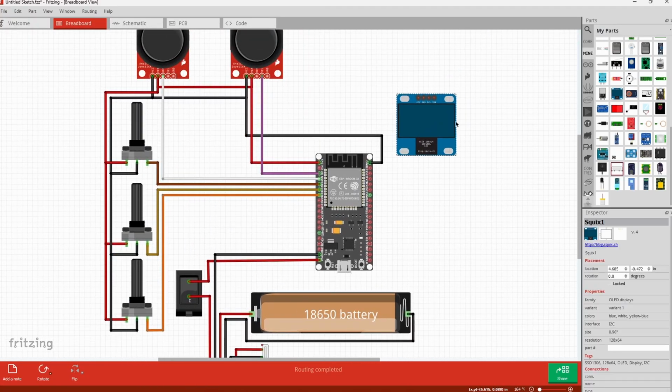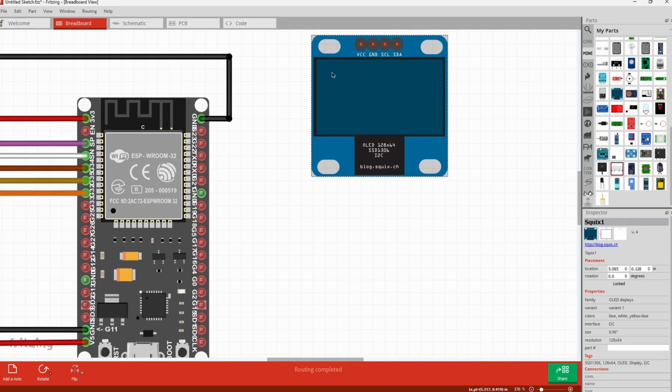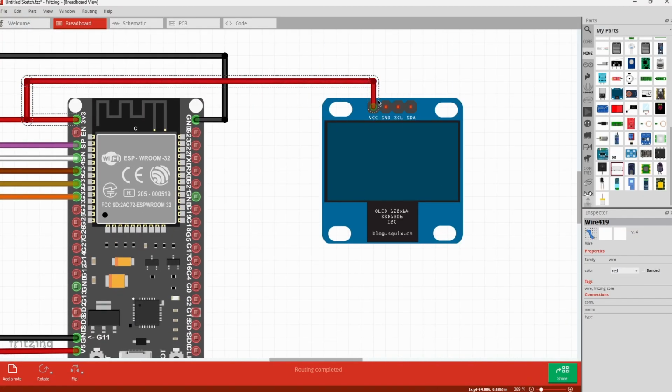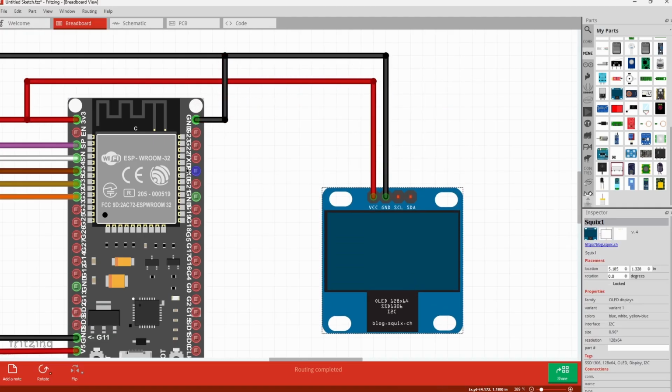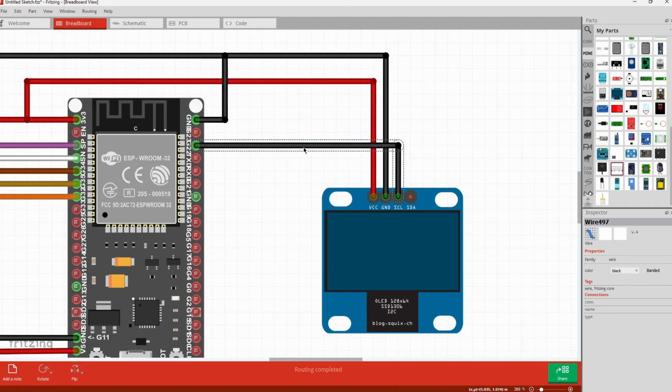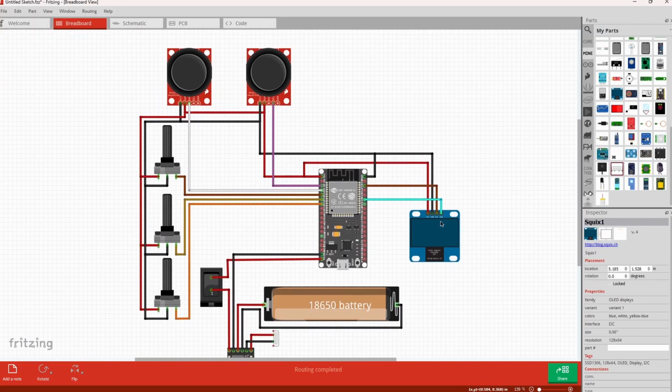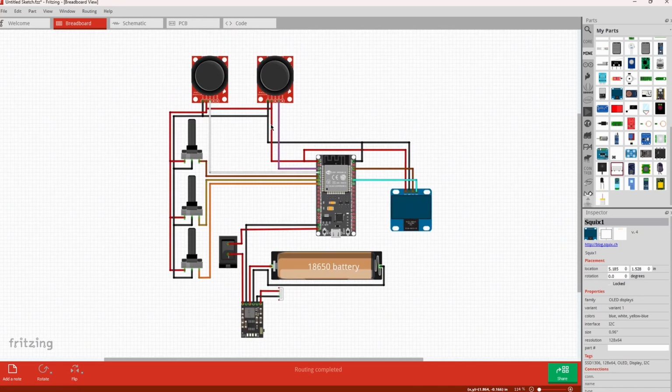Moving from there, the next thing I did was simply to connect the screen, which is an OLED screen that connects via I2C, I2C, whichever one you want to call it, just on the right. That just requires you to have an SCL and SDA pin. The ESP32 is obviously 3.3V logic, so I rather just run all my connections, all my sensors, everything off 3.3V, unless there's some component that requires 5V. That way everything is protected, your analog pins, all your pins are protected.